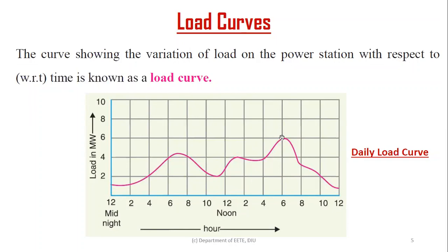With minimum capacity 6, it can give the power at that time, and in the rest of the time, in the day or night, it can definitely supply the power, because the demand is definitely less than 6 at the other times. So always remember that to select the capacity of a power station, we should select the maximum demand from the load curve, because the maximum demand gives us the minimum capacity required for the power station.